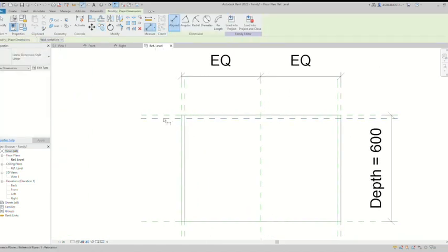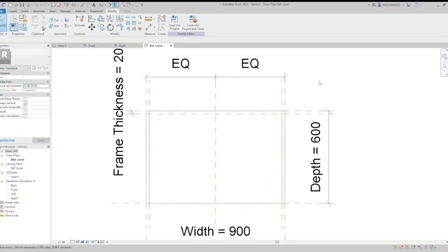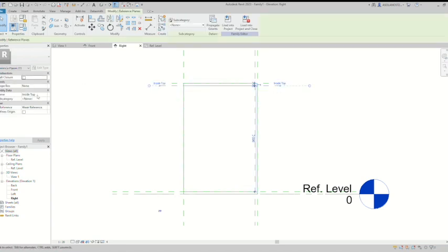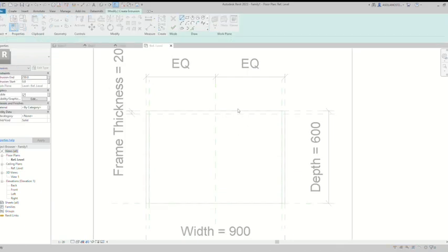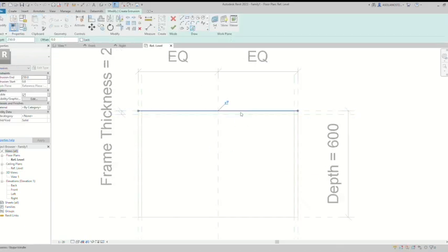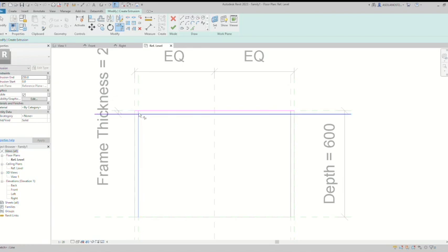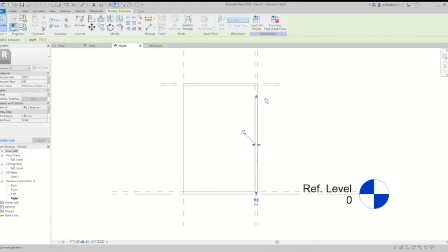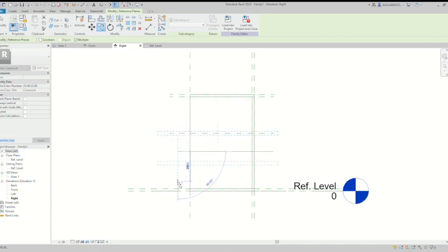And now we are gonna make the back panel for the cabinet. This is gonna have the same thickness as the other panels, but we have to create another reference plane called inside bottom in order to specify the good location for the back panel. Once we have finished it, we can create another extrusion to build the panel and adjust it like we did in the previous step.